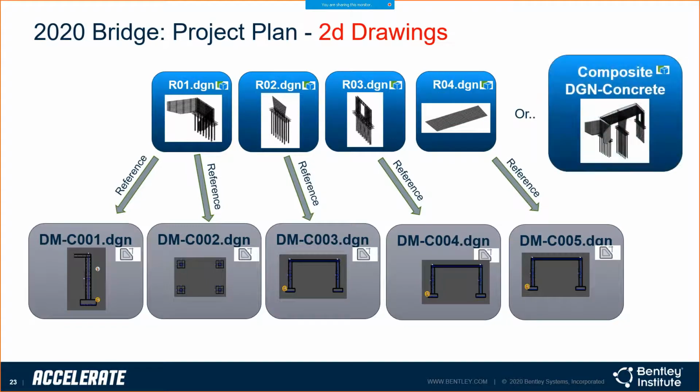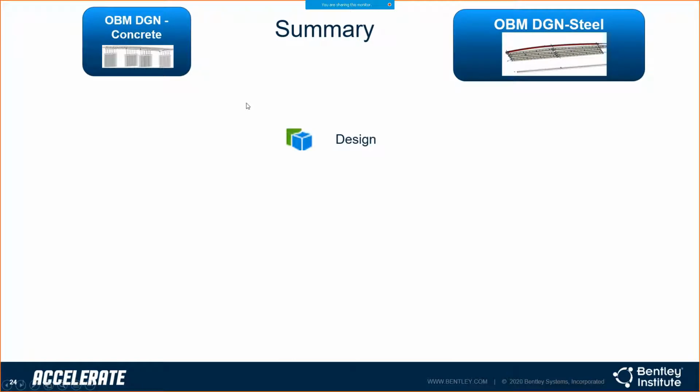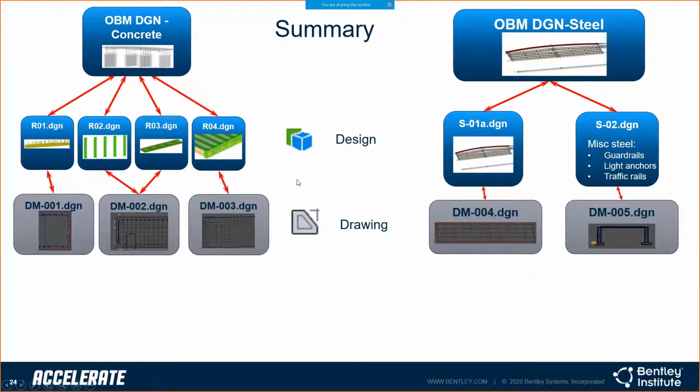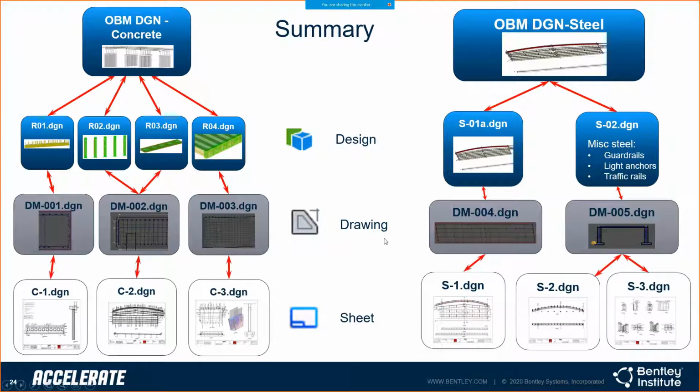And then from that, you could go about creating your sheets. Now, it is possible, since I can reference this stuff back to my drawing, I could generate the drawings from here as well. Again, no right or wrong answer there. But again, in summary, you're going to have a lot of design models. Your bridge itself is a design model. Any reinforcing you do, if you break those out to separate files, those will be design models. And then the drawing models will be generated from those using the dynamic view tools we talked about earlier. And then the sheet models will be references of those.